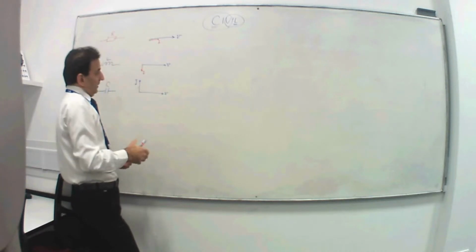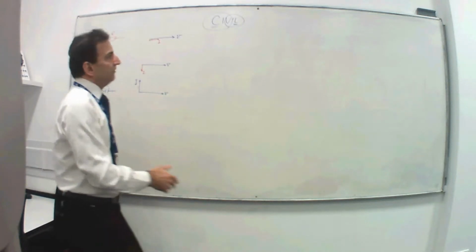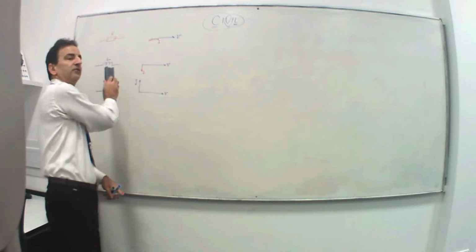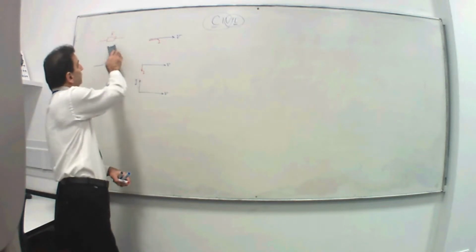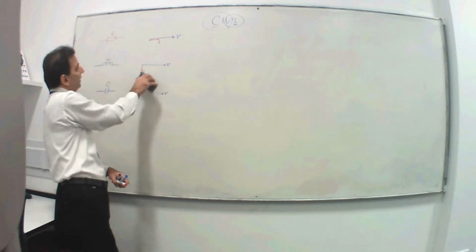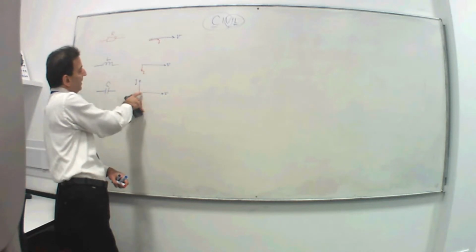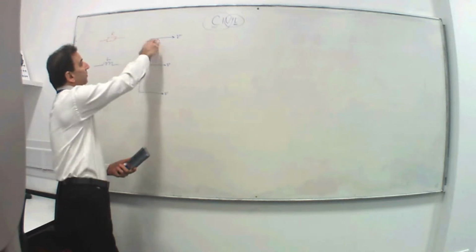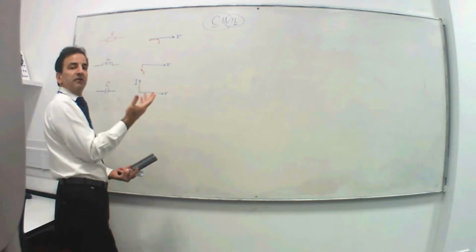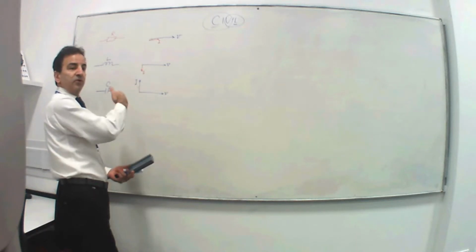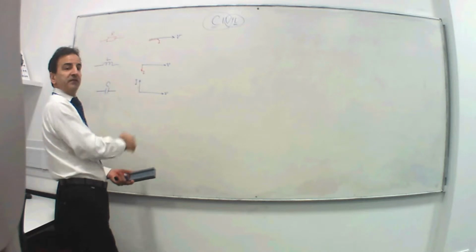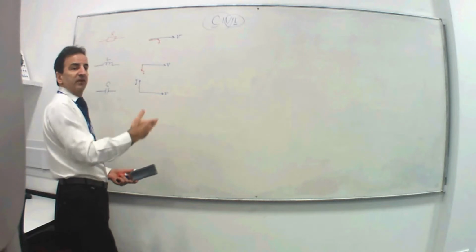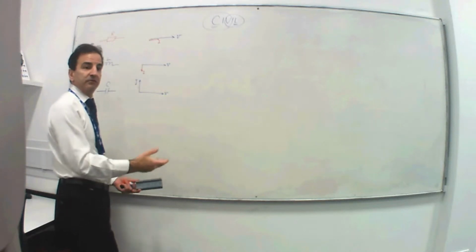Now, like I said, in reality, there's never purely resistive, inductive or capacitive circuits. So for these, the phase angle, which is 90 degrees here, is never going to be 90 degrees. It's always going to be between 0 and 90 degrees, either negative or positive, depending on which one is prevailing. If it is capacitive, then it's positive. If it is inductive, it's negative, whatever degree, 60 degrees, 30 degrees, whatever.